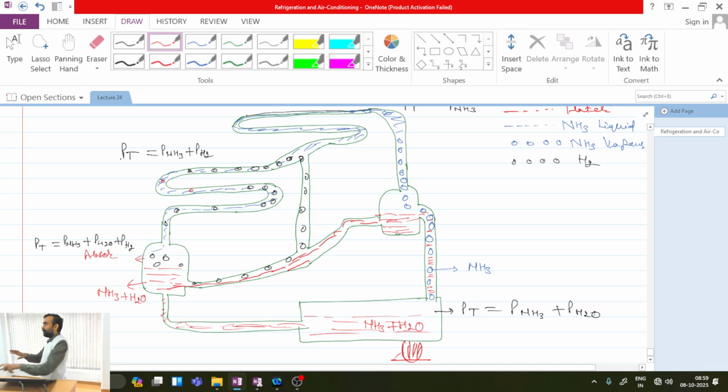Whenever a bubble rises in a vertical tube, it is not only the bubble separately moving; some liquid also gets attached to it, or some part of the liquid between two bubbles slides along with it. Why are these vapors rising upward? Because this is a gravitational system.